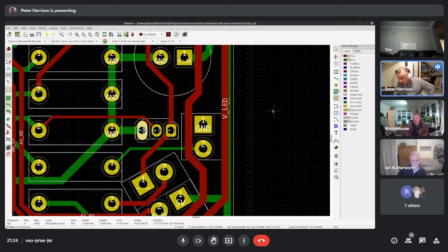And of note in that sense is, I think PCBWay and probably JLC PCB allow clearances down to something like 3 or 4 mils, right, which is absurdly tiny. So it's better to go big. Go for 8 and 8 or 10 and 10. And if you really can't fit stuff in at 8 and 8 and 10 and 10, then consider finer. The larger the spacing and sizes, the more likely it is to function and be made properly. But yes, good point.